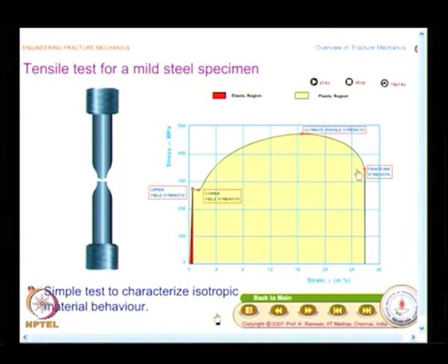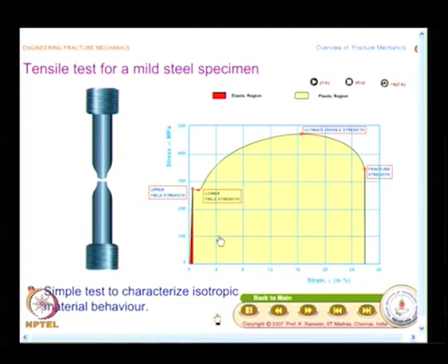The plastic region is very large in comparison to the elastic region, and as mechanical and aerospace engineers, you all know we design our structures such that the components remain within the elastic region. And what you learn from this graph is, before material separation, you have a very long safe zone wherein the material deforms plastically and gives you a warning. Before it separates, this is what you anticipate when you use a ductile material for structural application, but this does not happen. In the case of spectacular failures which I had shown earlier, structures made of ductile materials suddenly broke like glass. Why has this happened? What aspect was not modeled in the conventional analysis?